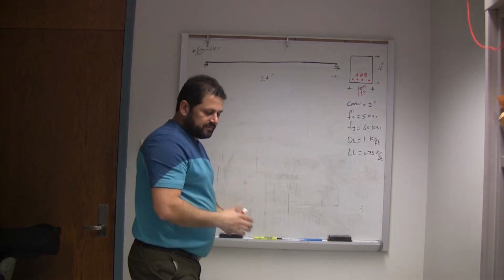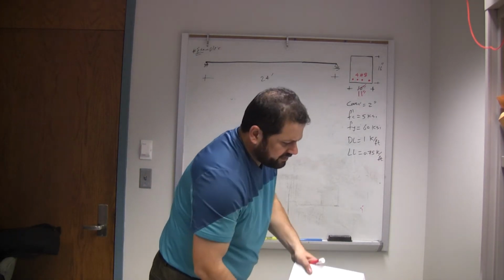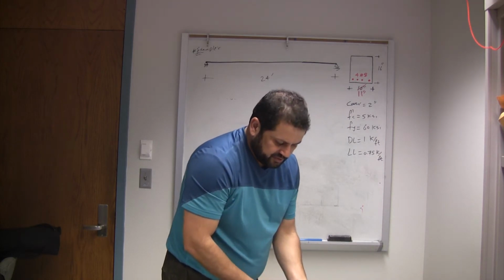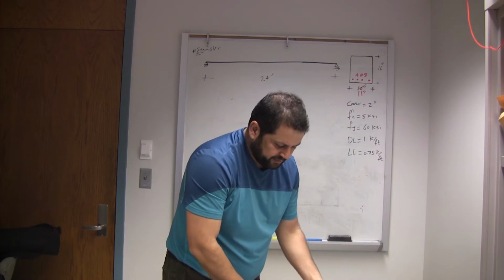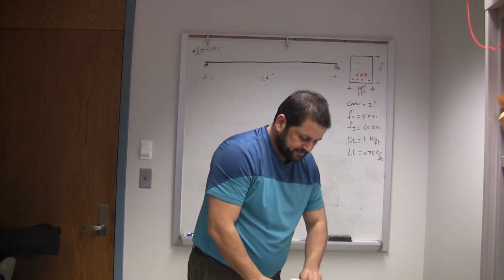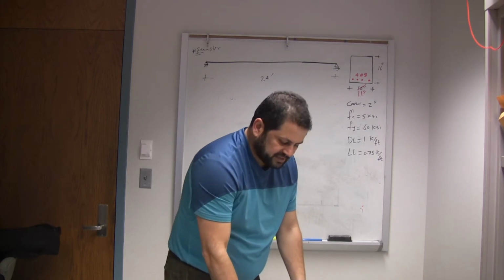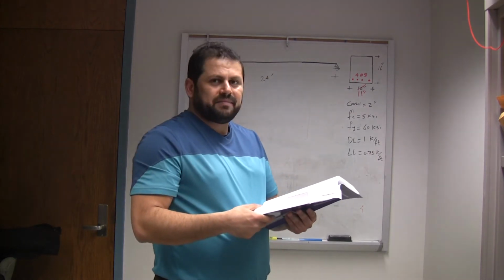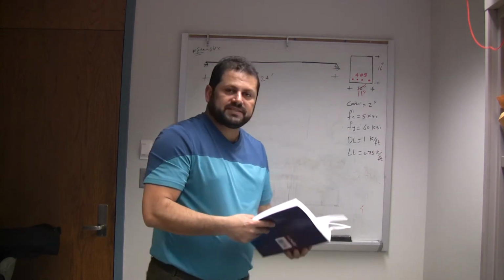So let's see this table. In most of these books, deflection is chapter 7. So the table I'm referring to for our class is 7.1. It says for simply supported beam, for deflection not to be checked in beams, the depth must be at least L over 16.